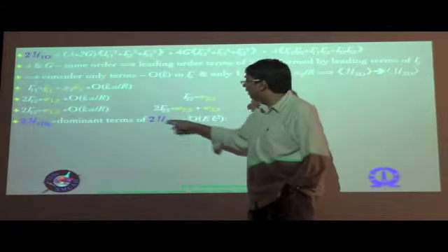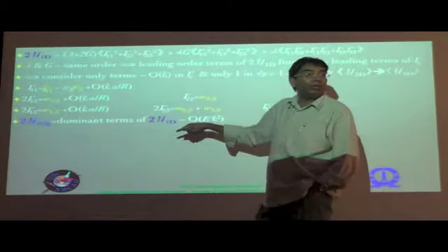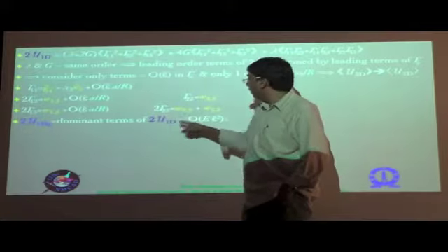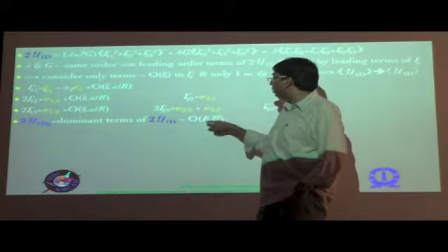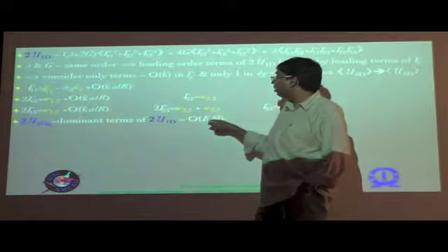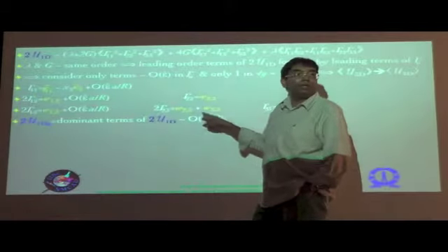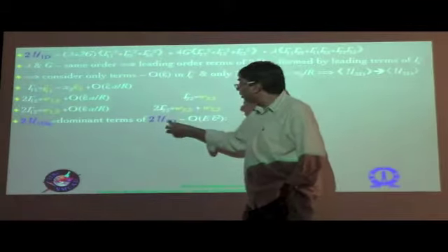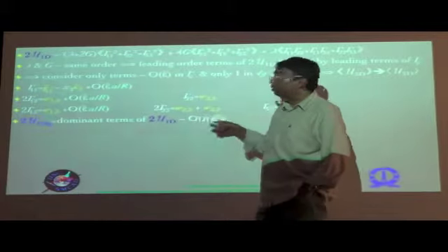Of course, when you integrate it, there will also be the area which is coming into the picture, because remember this is U1D. So strictly speaking, this should be E times A times epsilon hat squared, or what we call small a squared. Okay. So that should be there as well, because you're talking of U1D. If you're talking about U3D, then this would be correct.